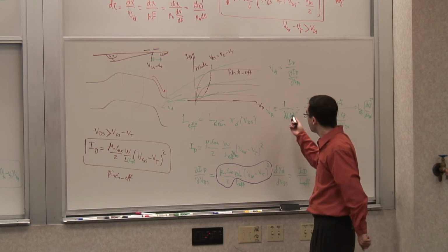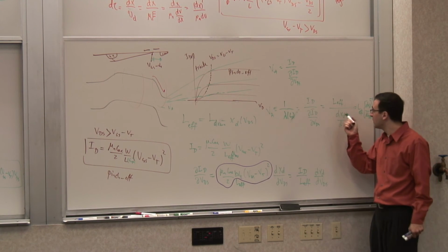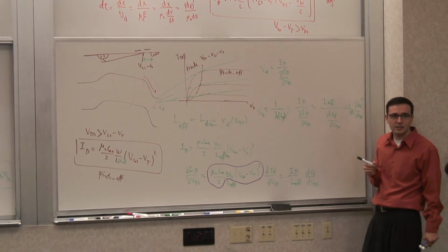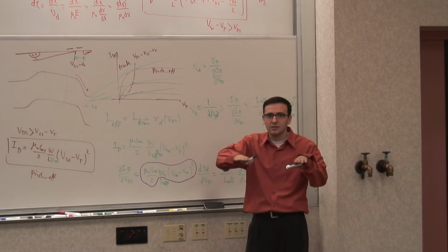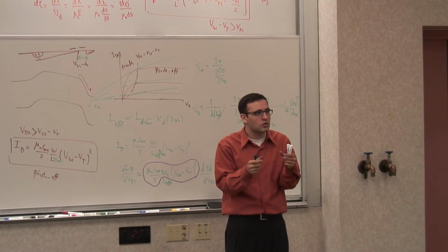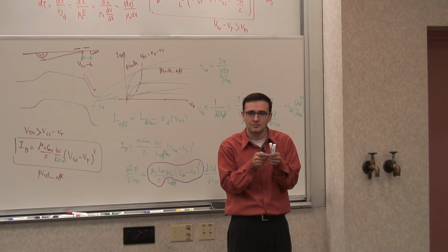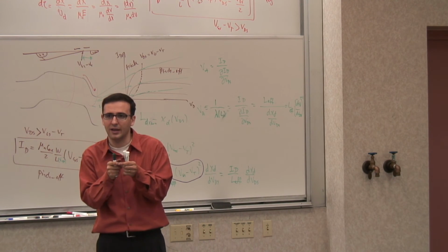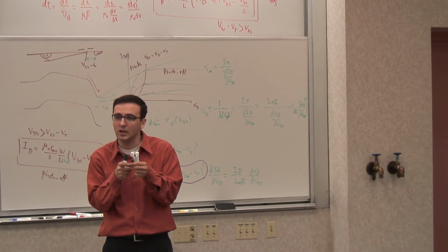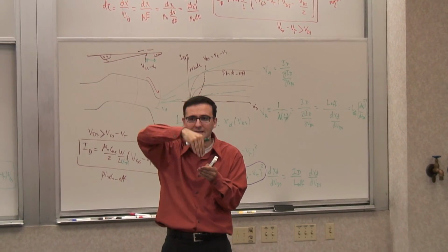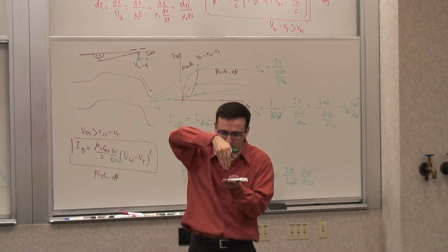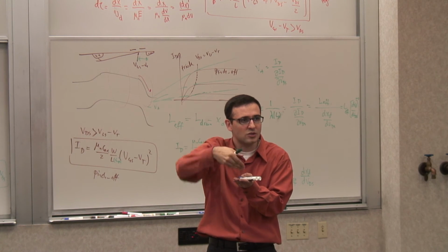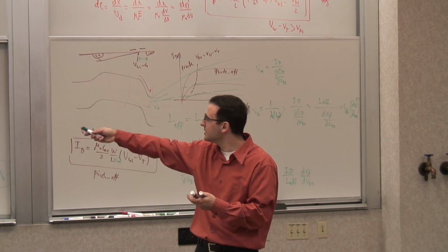But one good thing to remember is that, unlike the bipolar transistor, in a MOSFET you actually have control over this, because a MOSFET is a lateral device, a surface device. So you control both the W and the L of the transistor. In a bipolar transistor, you usually only control the emitter area. You can't control the base width, because, as we'll discuss later, it's usually built as a vertical device, in the bulk of the transistor. But here, this is done on the surface.